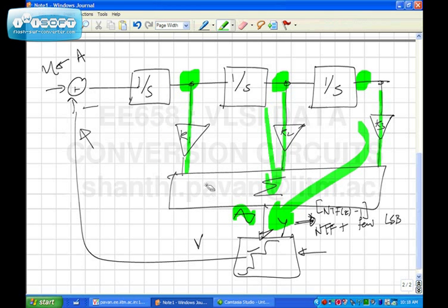But at this point, there is nothing you can say about what the maximum will be here, and here. The maximum amplitude at the outputs of each of these 3 integrators is still unknown. You can perhaps compute it given the input and all this other stuff, but the easiest way of finding out the maxima at the outputs of each of these integrators is through simulation.